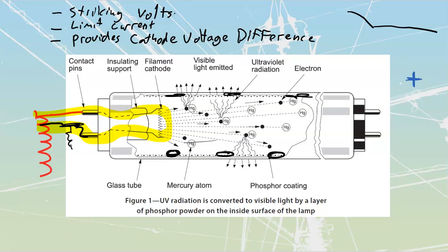You will still get the same ballast for the type of tube. You might be looking at a 40 watt, 48-inch tube. There are multiple different types of ballast, but they all operate the same, just some of them are going to be noisier than others.